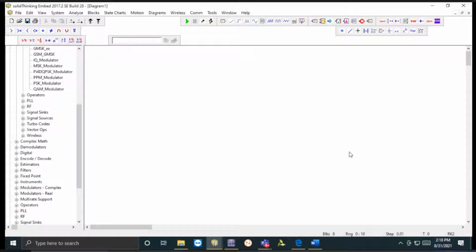So this is your Nyquist criteria in the time domain. And in the frequency domain, it is just the reverse. The sampling frequency Fs should be greater than or equal to 2 times Fm, where Fm is the maximum frequency component of the message signal, because the maximum frequency component will have the minimum period, right? So this is the Nyquist criteria that should be satisfied.